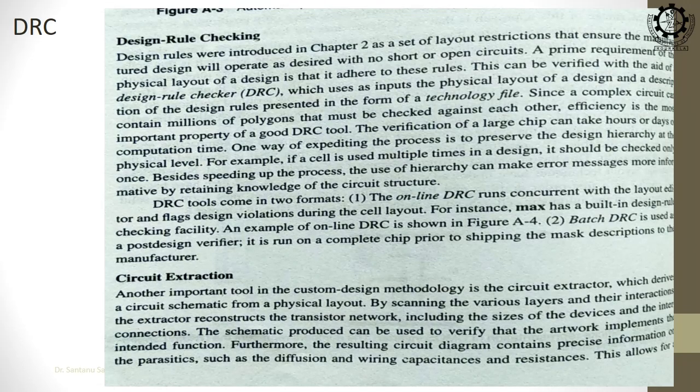These are the design rule checks that we just roughly discussed, that there are certain rules that you need to satisfy before you can pass your layout. Okay. So, first, your layout should pass all the DRC errors: the minimum distance between certain materials, minimum thickness, all these kinds of rules you have to satisfy.